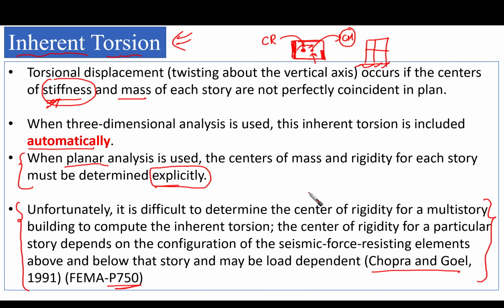Whenever we have a floor, and this floor has different lateral resisting systems at the left and right, for example, in a plan something like this, we have a shear wall here and another shear wall here. Sometimes we can notice that for the same floor, we have a thicker shear wall beneath the floor, however it is a little bit thinner above the floor.